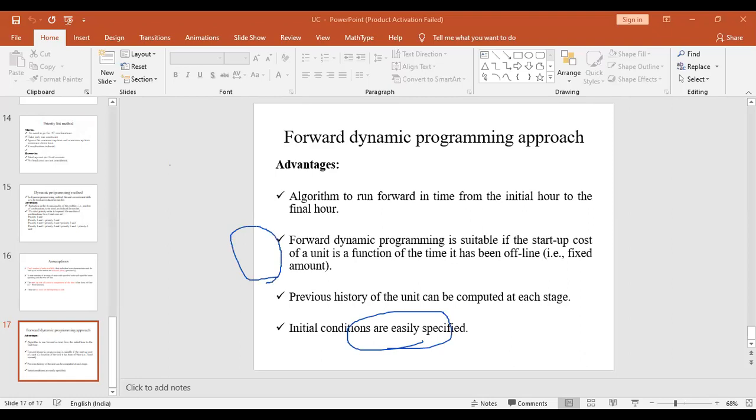The values obtained from the unit running in the system are plotted, and this simple representation can be used for calculating the input output characteristics of the systems. These characteristics can be expressed in millions of kilocalories per hour, or in rupees per hour, versus the output power in megawatts.